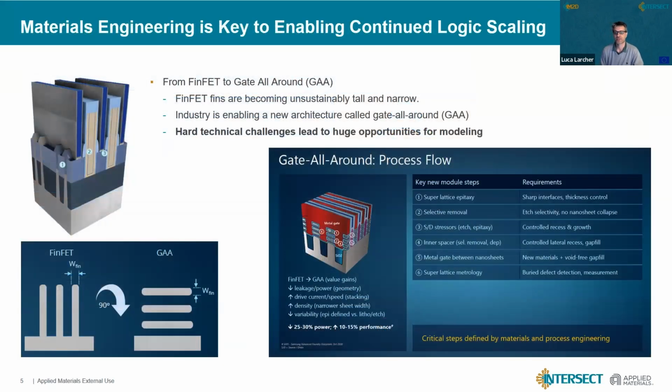instead of going directly to the experiments. And of course, as I was saying before, the electronics is going 3D. We have DRAM, I already showed, 3D NAND, I will not show, but the 3D NAND was the first case of memory going really, literally, 3D. And the last but not least important one is that right now, logic transistor, logic FET, moved from FinFET, which was partially 3D, to a full 3D structure, which is typically called gate-all-around and nanosheet. This is, again, another huge, big revolution.